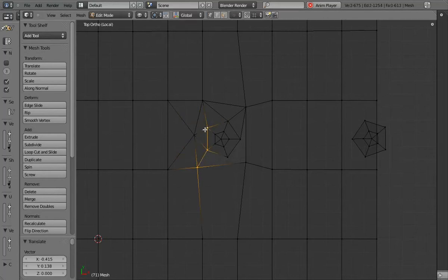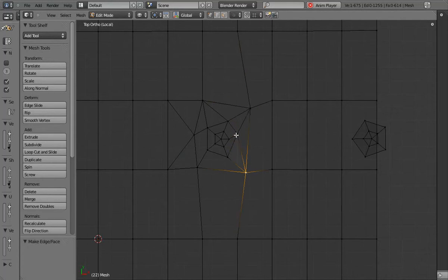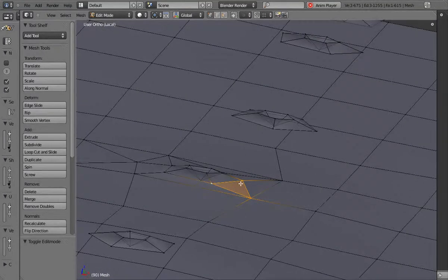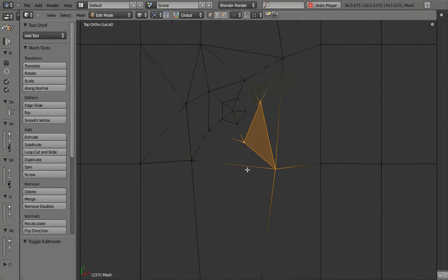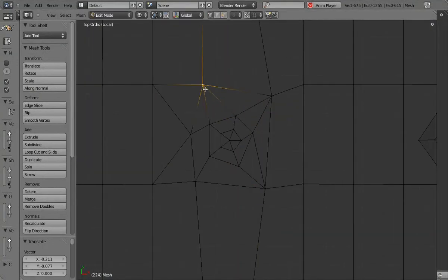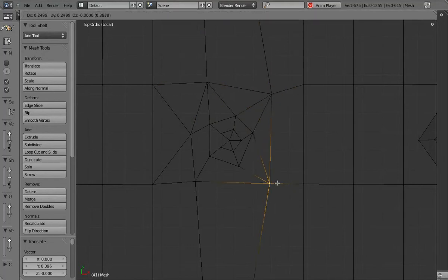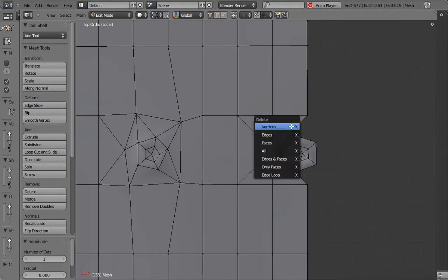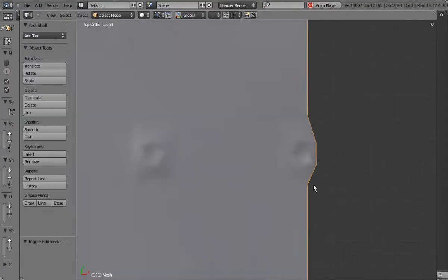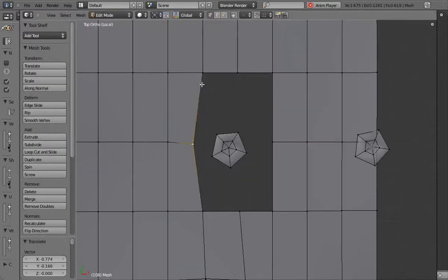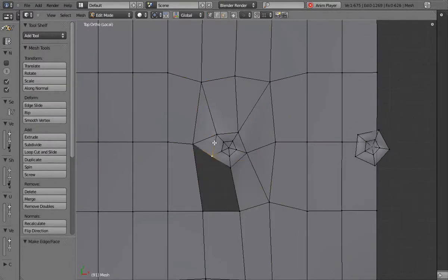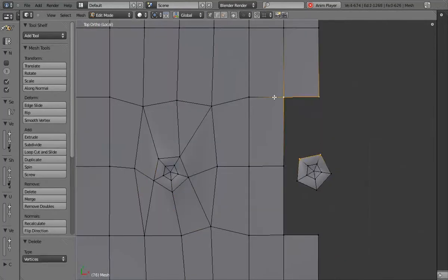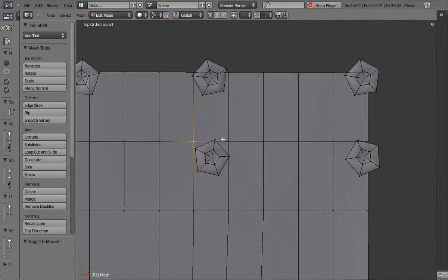And how I did that was just I erased one or two of the faces that are around these bumps, and now I'm just going through and manually facing them together, 3 or 4 vertices at a time. I add a few subdivisions here and there just so that the facing is nice and clean. If the facing on low poly objects is messy, or if the angles of the faces are too extreme, it's going to make the geometry look like hell when you're actually in the game.